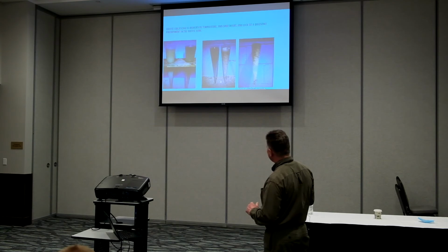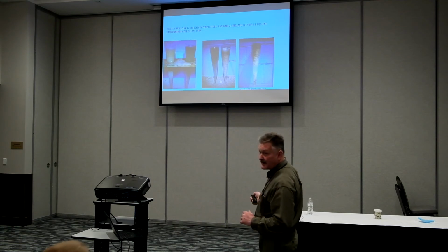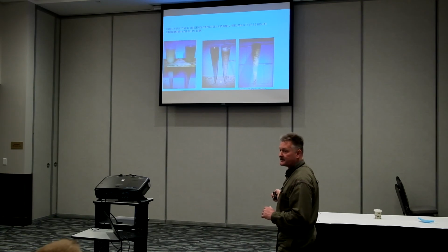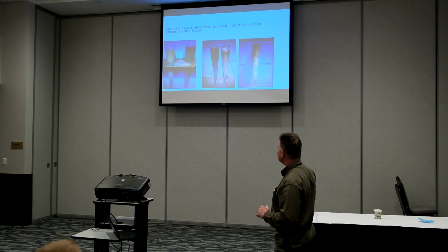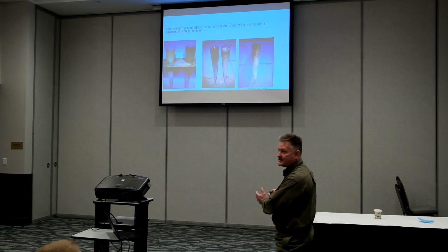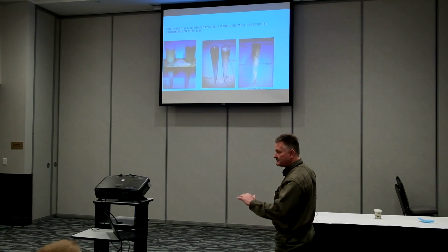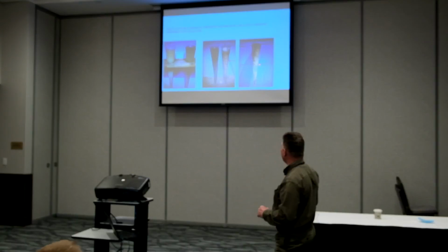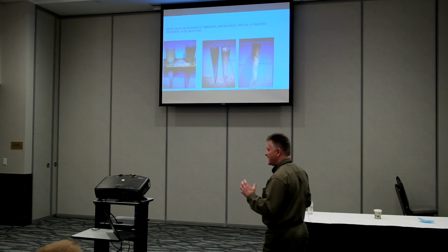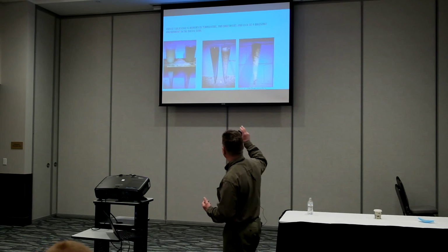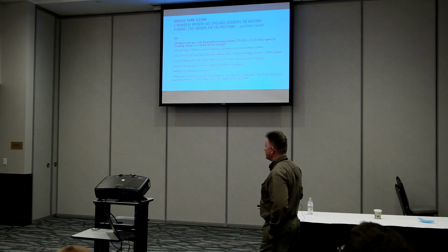This was a sample collected on a Monday, and temperature is pretty low, about 75 degrees. Say we went back out there and sampled on a Saturday during the peak flow events in this restaurant. Temperature is 102, and you see it just carries out that fat, oil, and grease. Once it starts cooling, as you can see in this example, it starts coalescing, separating, and floating up. So when we sample can have a big impact on the size of our tank, and the quiescent zone has a major impact.